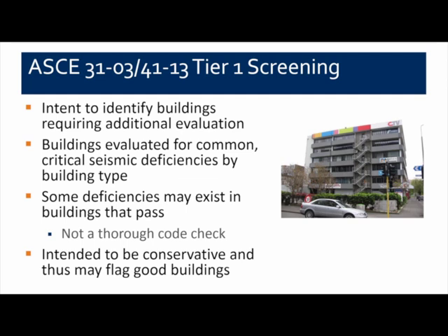So we're not looking at every deficiency that might exist. It's not a thorough design evaluation of the building, so there could be some deficiencies that occur in the building that would not be identified by this Tier 1 screening. This methodology is intended to be very conservative and may actually flag buildings that are good as potentially hazardous. So it's important to realize that buildings identified as not passing Tier 1 are not necessarily bad. It just means that they need further evaluation.